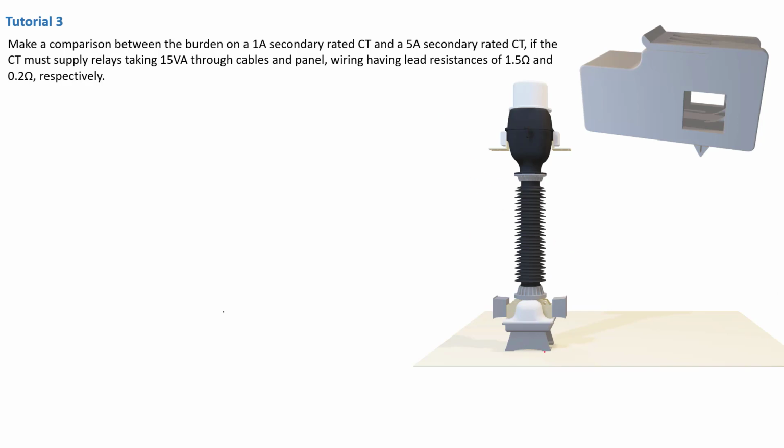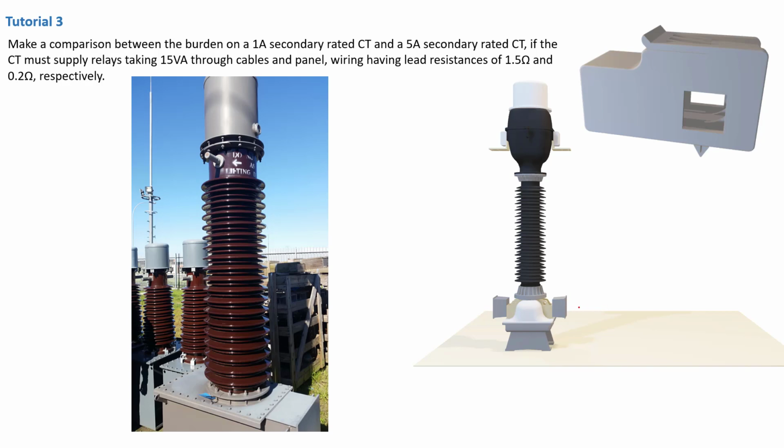These electrical equipment are usually found on transmission substations or distribution substations. They serve two purposes. One is for metering purpose. That basically means they reduce a high level current to a low level current that can be measured, and they also serve the purpose of protections. That is, they send signal to your relays, and your relays then trip the circuit breaker in case of a high voltage fault on your system.